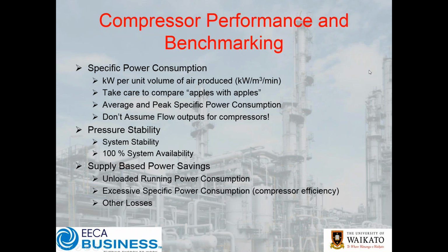Now something that we want to just highlight very, very briefly today. We'll go through these sorts of opportunities in more detail in future webinars, but something for you to think about and be asking questions about is, what is your kilowatts per unit volume of air produced, or the specific power consumption? Now you'll have what you might call a nameplate number, but does that actually account for all of your upstream filtration and all the other ancillary loading, cooling fans, etc.? What is your actual true power consumption per unit of air produced?